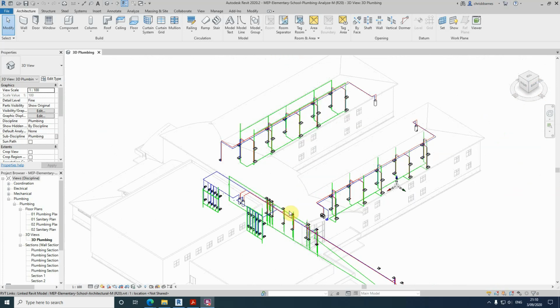You can draw the pipes independently or using connectors in the fixtures. Pipes can be drawn in plan, elevation, section and 3D views. To get the pipes at the right height, it is recommended to start from the connectors in the plumbing fixtures. Fittings between changes of height or size are automatically applied as you model the elements.